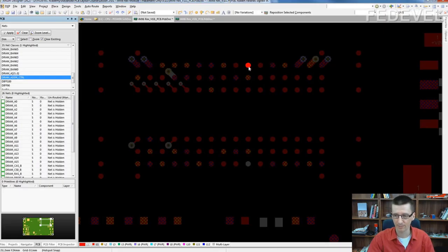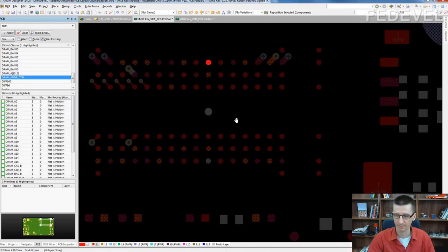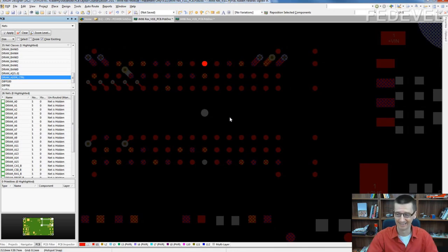That may look very simple. Once you place a through hole via exactly in the middle between these 2 parts, you will have exactly the same distance between them. Ta-da! Problem solved. It's not so simple. I'll show you. Do you know how many signals we need to connect this way? We need to connect 26 nets which are in this group.